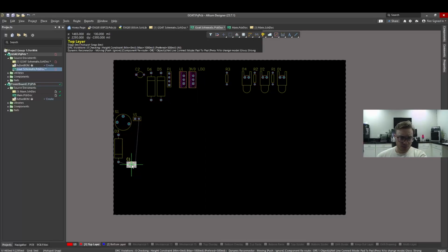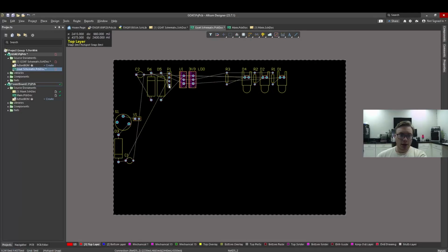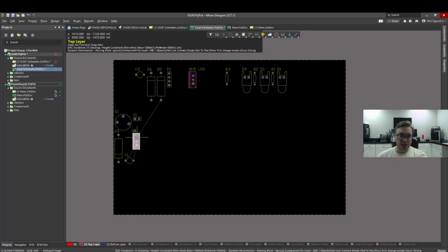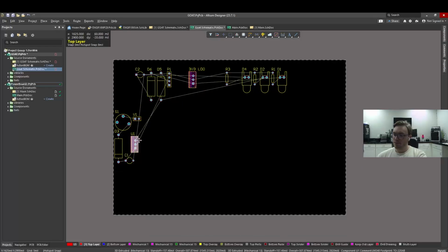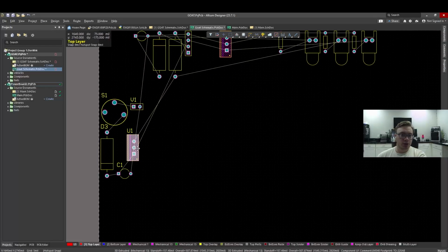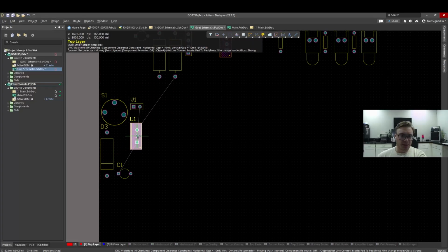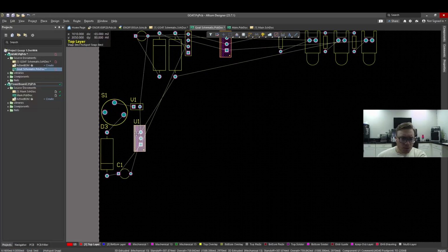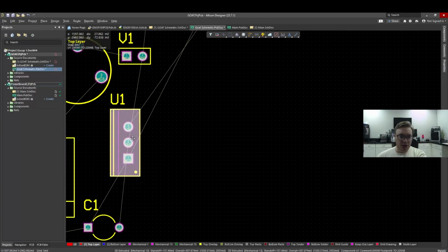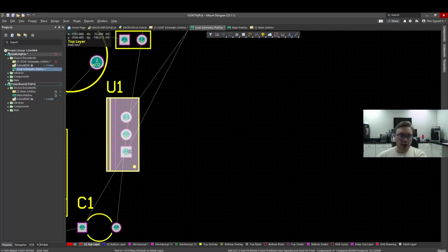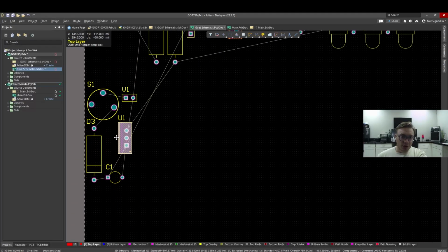So we'll put that down here, and trying to think about how I did this last time. I don't really want to just do the exact same design over again. Make it a little bit of a challenge. But I also want it to be close enough that they still resemble each other, obviously. So if we see on this 5-volt LDO, the middle pin is ground. And this bottom pin here is VCC. So I'm wondering if it would be best to...